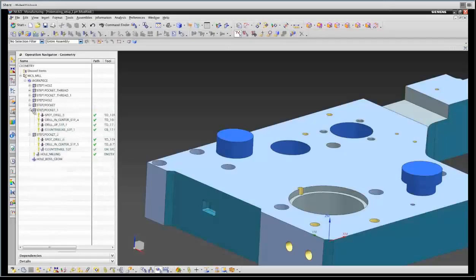So it created a whole boss geometry group over here in the geometry view, and now when I go to do that, I will select the geometry as my whole boss geometry, and now it knows what I'm wanting to cut. So we'll call this hole milling, and we'll actually call these holes. Should have said boss on the other ones, but we'll know what it is. So now, how do I want to cut these?